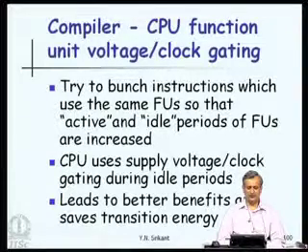This technique can be used both for voltage gating and also clock gating of the CPU. The CPU is active for some time, right. Now, we try to bunch instructions which use the same function unit, so that the active and idle periods of function units are increased.